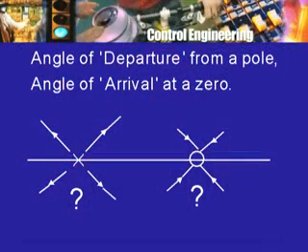Now using the angle condition, namely the sum of angles at the poles minus the sum of angles at the zeros is an odd multiple of pi or 180 degrees, using that condition for points very close to the pole or to the zero, you can find out the angle of departure and the angle of arrival at the poles and zeros respectively. It will take some time to go through the derivation of the rule, but you can look it up, and it is a fairly simple rule about the angle of departure and the angle of arrival at the poles and zeros.